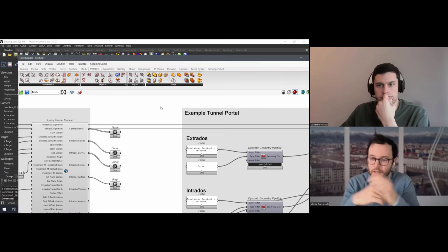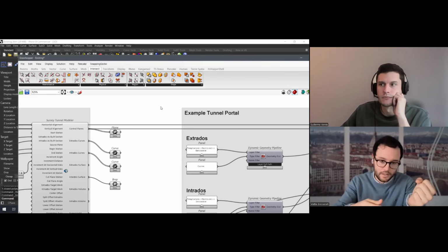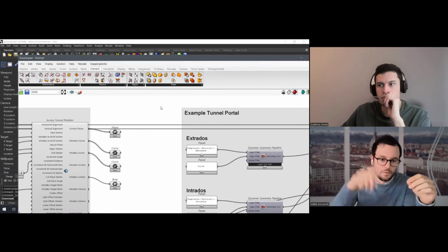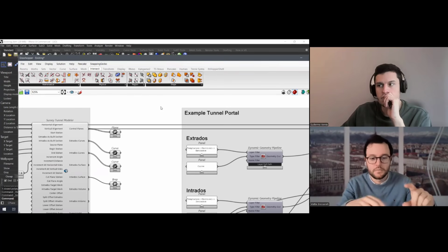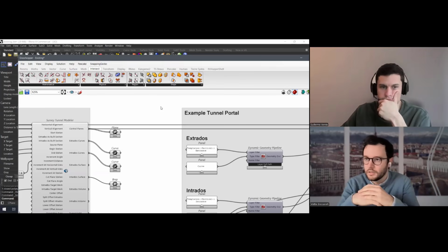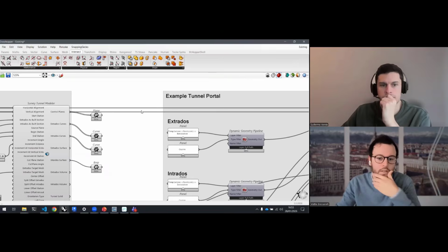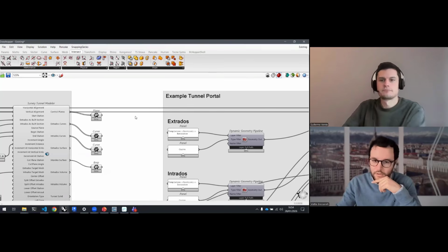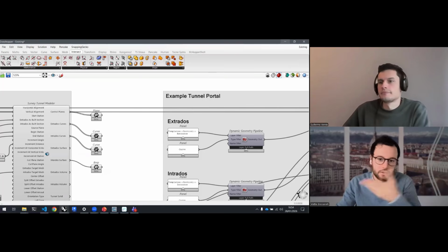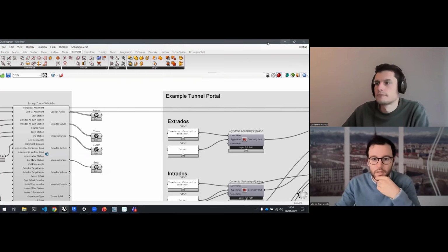We also did this: when you cut the surface, if you put proxy lines in it, like the characteristic lines of the road, you can also compute dimensions, place them, bake them in the Rhino scene, and when you move them to AutoCAD, they will work. The only tricky thing is annotations, but they are translated as well. So yes, we did that for a couple of tunnels. If the client needs CAD drawings from it, that's what we do. Otherwise, you go to Revit or different targets, depending on the client and project requirements.